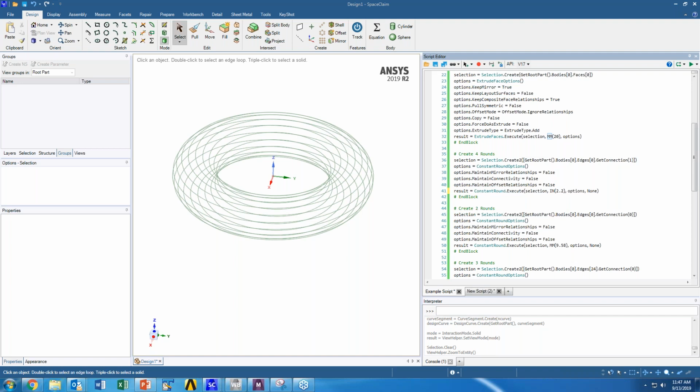I actually have done this with a separate script where we essentially have used the Workbench run script option and just inserted the respective script to have it generate the CAD automatically, kind of in the background in SpaceClaim, rather than opening SpaceClaim, generating the CAD, and then updating. The script there just kind of sends the script to the SpaceClaim executable, creates the CAD, and brings it back without all the associated visuals.